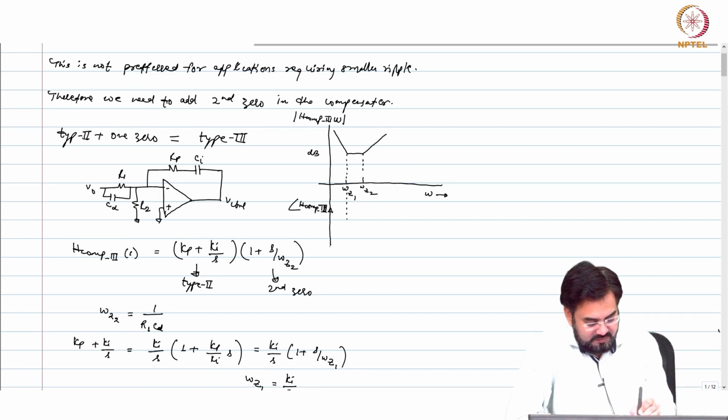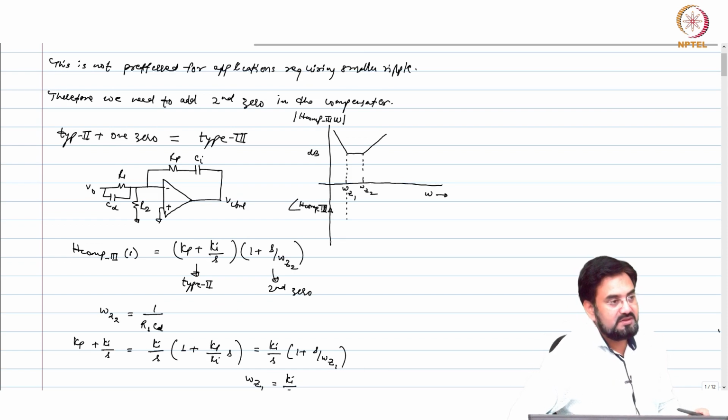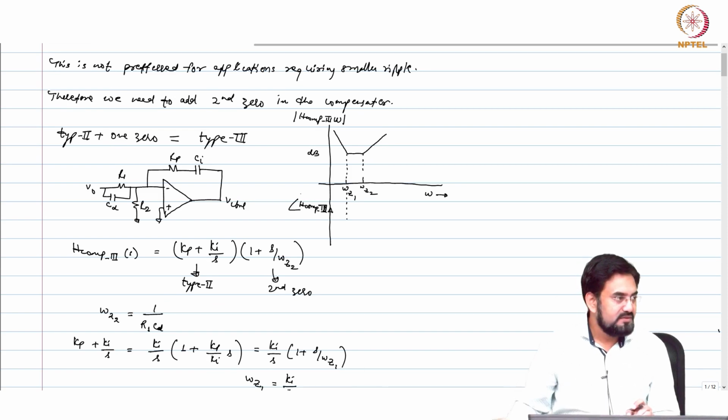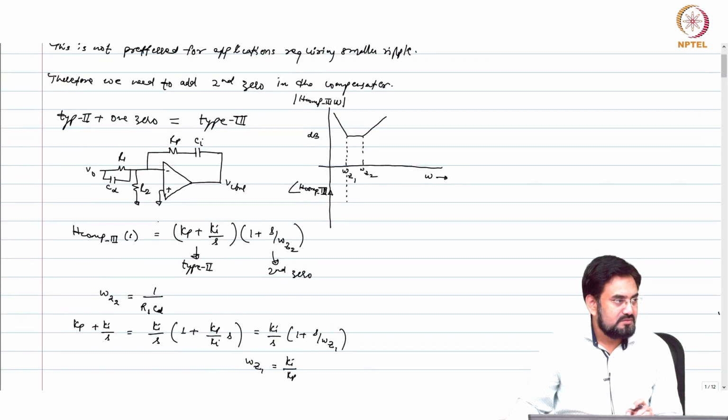So what about the phase? How will it start? Start from minus 90. Minus 90, or is it inverting? Minus 90 plus 180, so 90 degrees, full edge of 90 degrees, because we have a negative sign. Okay, 180 degrees minus 90 degrees.